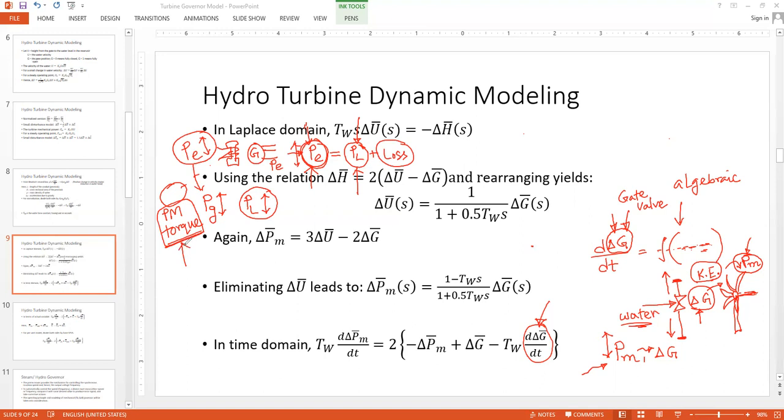And that torque of the prime mover is actually dependent on, if it is a hydro generation system, then this is controlled by del G. You get the point? So if we can have the dynamics of del G available, if we can model it, then we are done almost. This job is done in real life by a device known as governor. Have you heard the name governor? It's not the political governor. It's the mechanical governor, the governor that governs the power flow. It controls the gate positioning of the generation systems, steam governor or hydro turbine governor, etc.